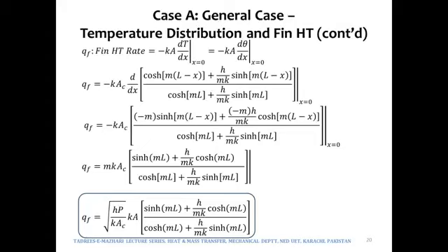Fin will transfer the same amount of heat as it will come into it if the system is working under steady state conditions. Of course, fin will not transfer more heat than is coming in, that is out of question. And unless there are some special arrangements, fin will not transfer less heat than what is coming in, because if it does so, there will be energy storage in the fin and the system will no longer be under steady state conditions.